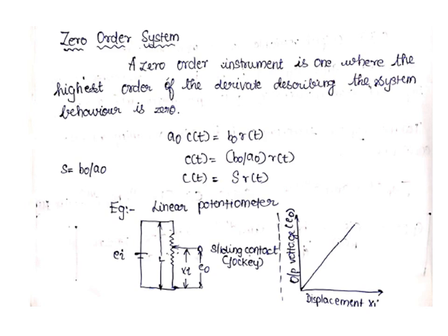This is EI and this is the length of the potentiometer, and based on the displacement, only this amount of voltage is going to be connected to E naught. You can please check the PPT I am showing here. Then this is going to be the output voltage and displacement Xi graph. This is going to be linear, so this is the example of your zero order system.